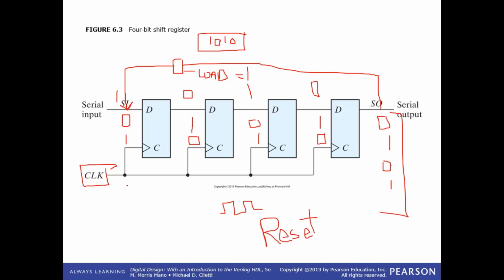I do not want that this 4-bit shift register works 10 microseconds after the previous 4-bit register. If I have millions of 4-bit registers, I would just want each and every one of them to respond to me at the same time. By placing an AND gate over here, a switch over here, the clock would be delayed. The clock would be given a propagation delay, even if the gate is on or the gate is off. And I do not want that.